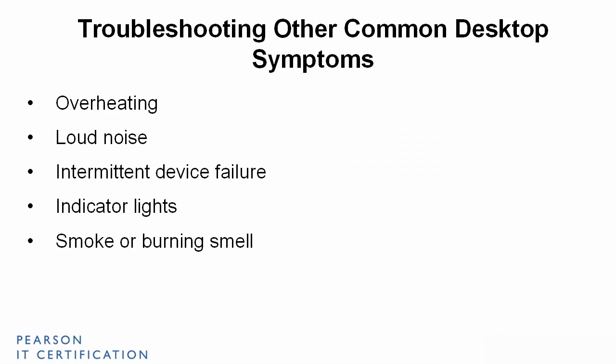Now, sometimes the fan will fail on the power supply. That's a possibility as well. And it's possible that the CPU could overheat and cause a burning smell as well. That's when it's too late for the CPU, most likely that'll have to be replaced. But generally, it's a power supply issue. So you want to really replace that if you ever see any smoke or smell any burning types of odors.